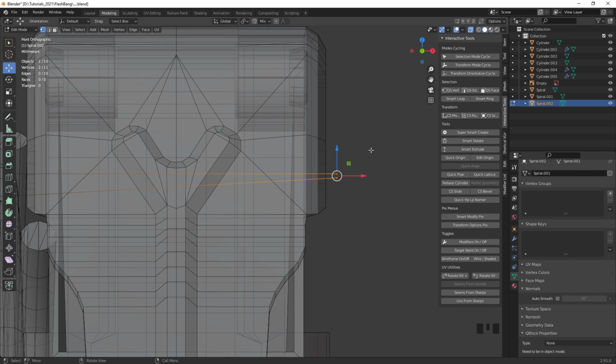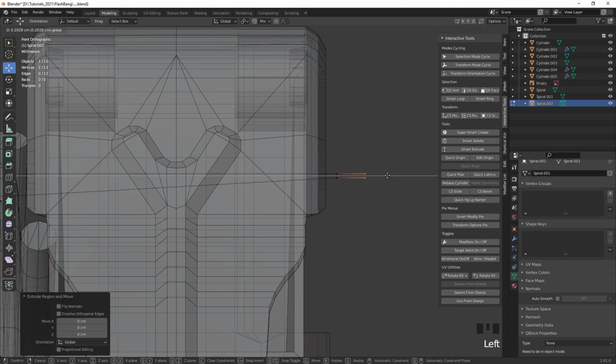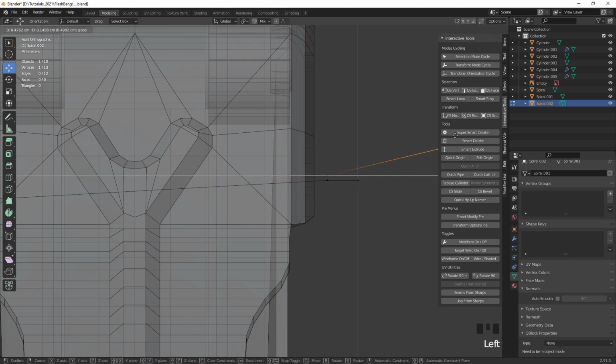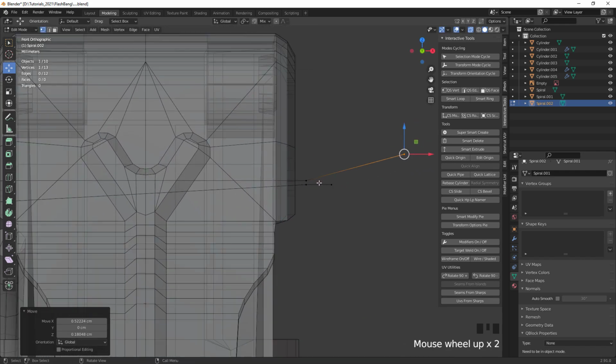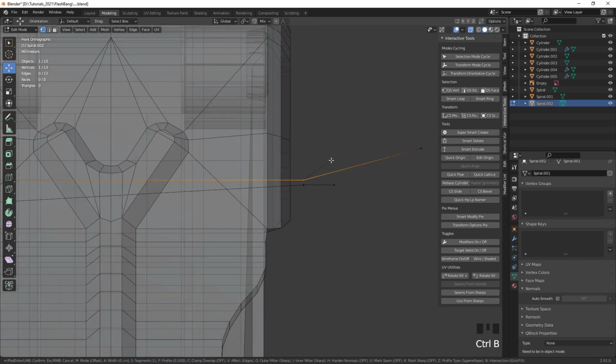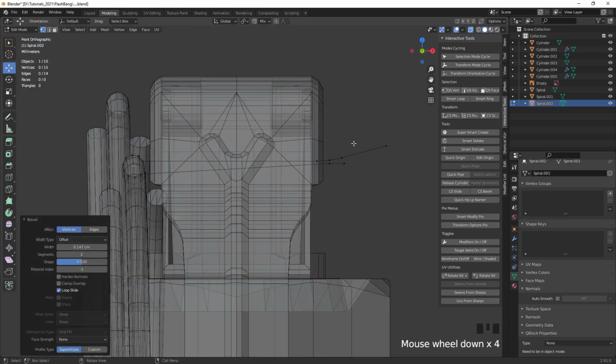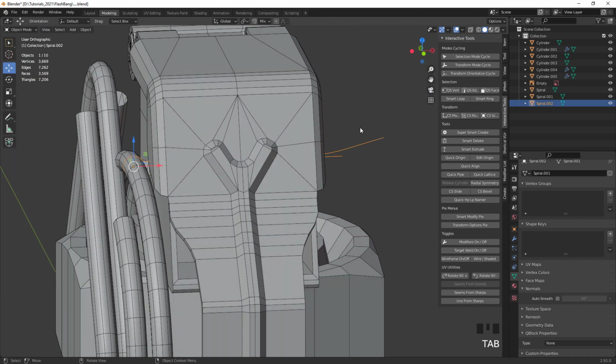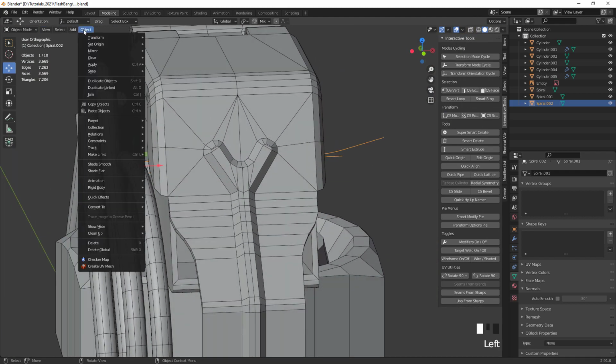And then we can extrude that out here further. Snap it back, then pull it out there, and this one here I'm gonna take a bit further up here, and this one here we can then extrude, no actually bevel, Control B and V like Victor,